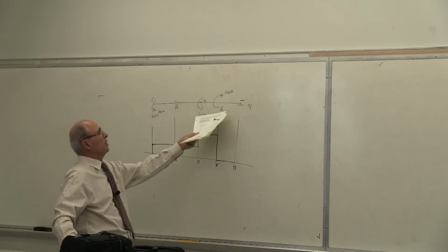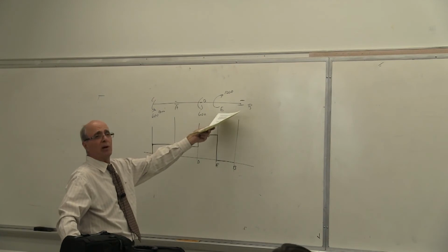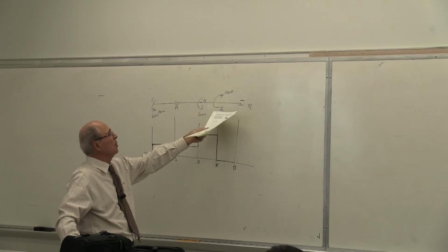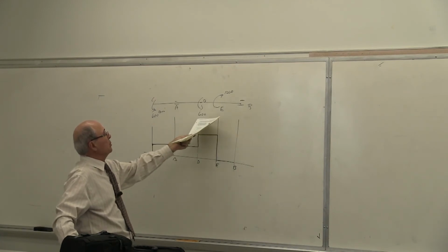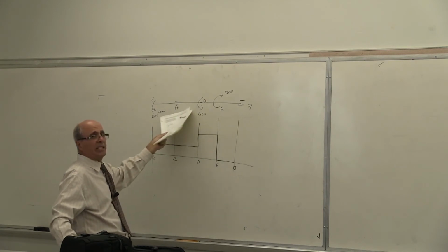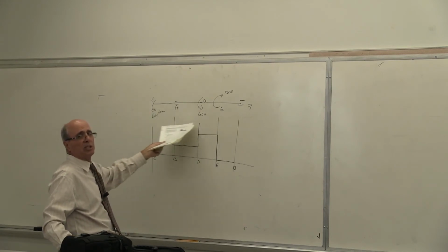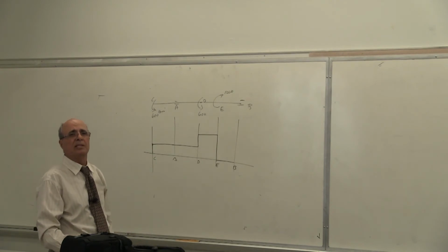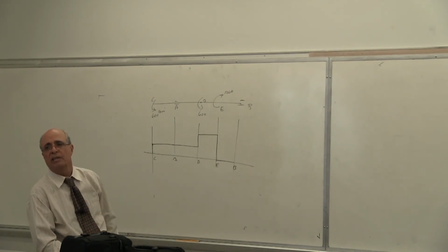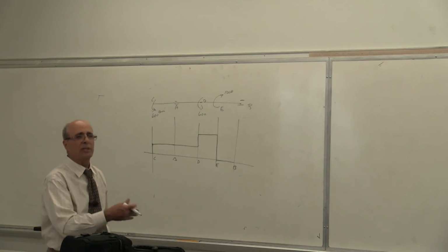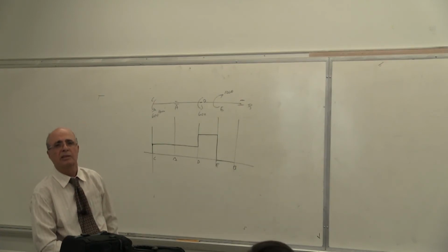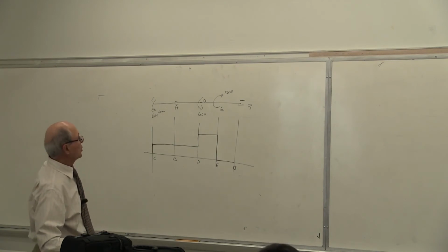So in other words, if this is the generator creating 1200 unit of pound inch of torque, there is a motor running here and a motor running there, they're taking away. They are the cutting machine and sewing machine, each one takes 50% of that. Is that correct? The balance is 0. Is that correct or not? Yes? This is how the shaft works. You create the torque and somebody uses it. Is that correct or not? Yes? Well, that's your torque diagram.